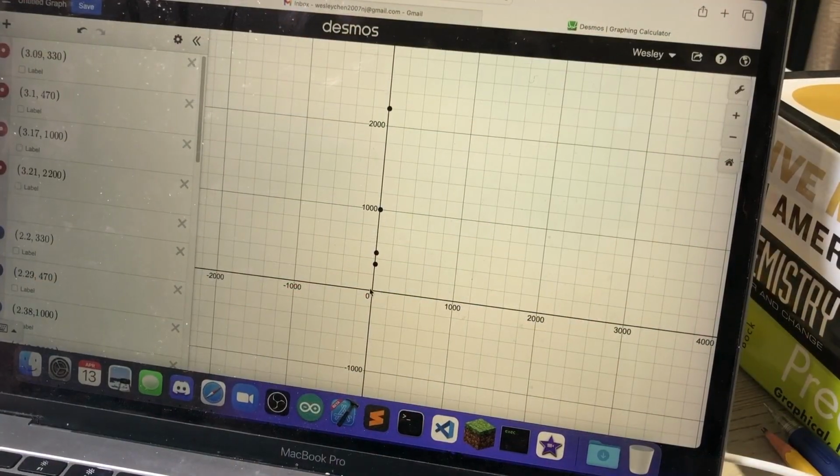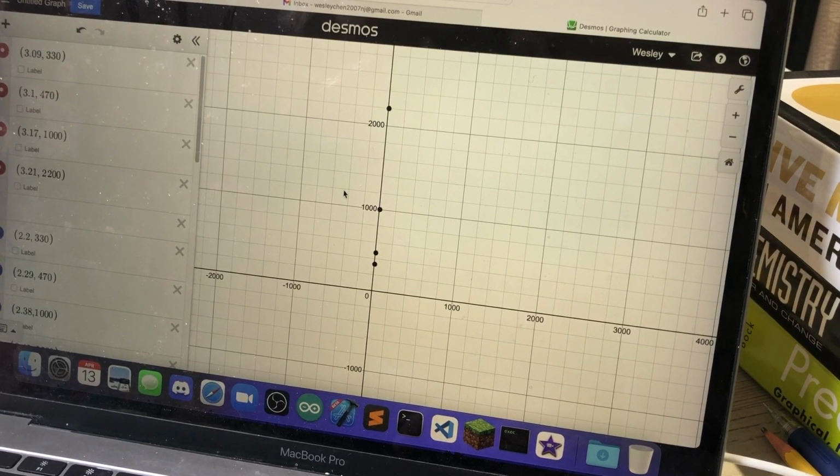So now that I finished recording all the data, I've put all the data points into decimals. Now does this look like anything familiar to you? Probably not. And it doesn't look like anything to me either. So let's change these a bit. Here I have recorded the voltage and the resistance. However, the voltage is across that of the resistor, and we only want to know what's across the diode.